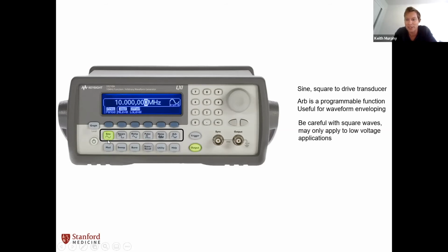Typically, you'll use a sine wave because we're trying to smoothly oscillate the voltage across the crystal to get nice smooth expansion and contraction. You can also use a square wave because, in the same way a sine wave works, you're going to get your positive and negative voltages. Although this can be dangerous at extremely high voltages because it can cause the crystal to expand or contract faster than it's really built to do. So you're talking about the fundamental frequency, right? Something like 500 kilohertz. Yep, whatever your fundamental might be that your crystal will oscillate at.